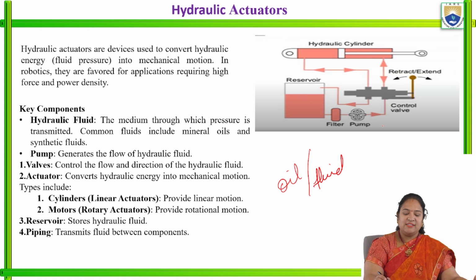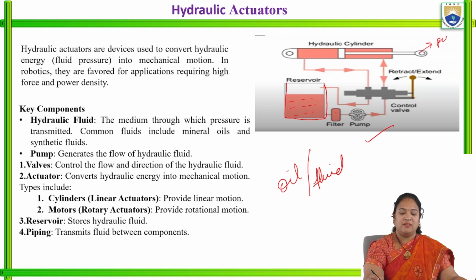Then we can see a figure here. This figure shows the hydraulic actuator, where we have a reservoir in which the fluid is placed. This reservoir is attached to the filter, the filter is attached to the pump, and from the pump the fluid moves to the hydraulic cylinder, where we have the piston or shaft placed.